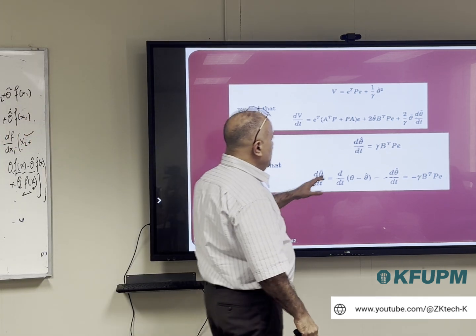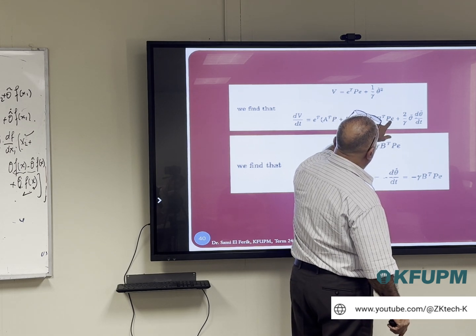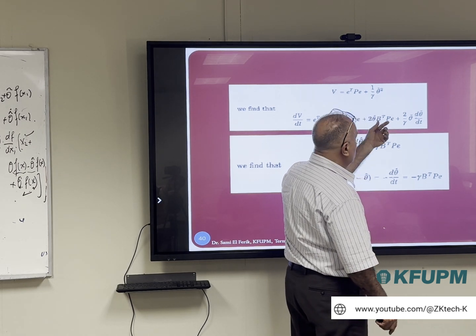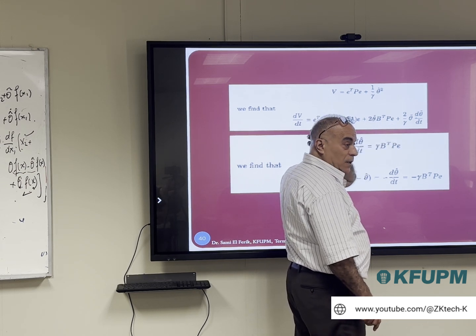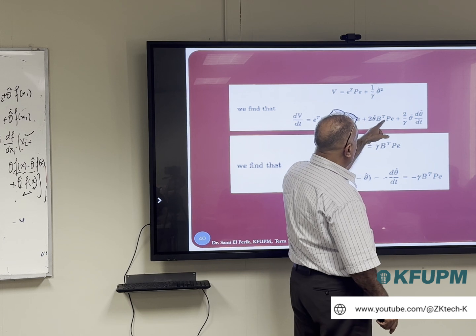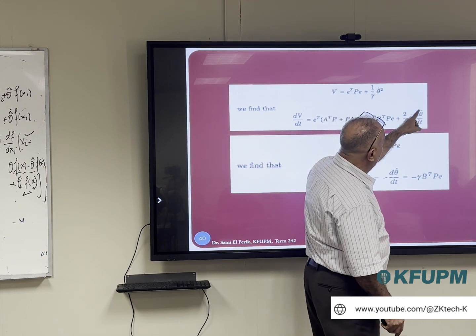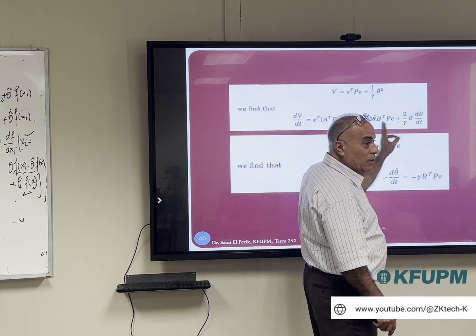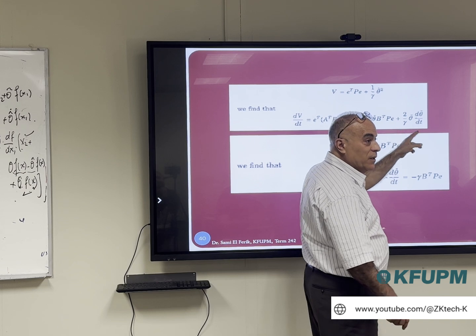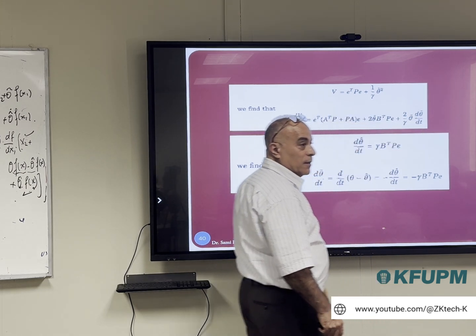The advantage of this is that B transpose P multiplied by E that you are seeing here is a scalar value. Since it's a scalar value and this is a vector theta tilde, the derivative of this is also the gradient, right? So we are able to find the value of each derivative there. But we need to have the transpose appearing in the equation. Okay?